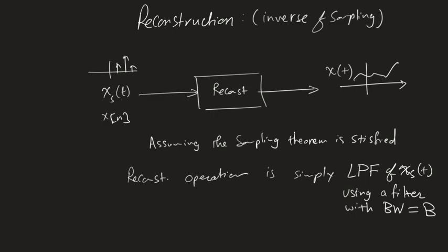And the filtering, don't you apply it to the frequency? The filter, you apply to the frequency domain and then you have to do the inverse. Again, when you do the inverse and stuff like that, it's just how you look at things. But what you do in the frequency domain happens in the time domain, the correct way. When I go to the frequency domain and I filter a signal, it is actually, from a time domain perspective, producing the correct output, right? It's only which one I look at. Again, it's as if this is your signal, and we said it has two perspectives. This is time domain, this is frequency domain.